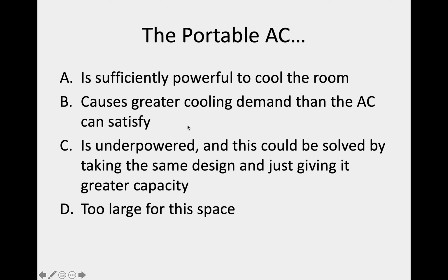Now, many of you have experienced these devices, and you would say, but they work. I feel cooler. And the answer is they often are successful at cooling the room that they're in or blowing cold air on the person that they're blowing cold air on, but they're transferring that heating or cooling demand to other parts of the building as it sucks in air from outside. It may be sucking in cooled air from the next room that maybe has a different kind of air conditioner, but it's adding to the overall heating demand or cooling demand for the space.